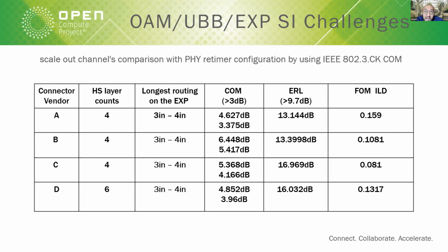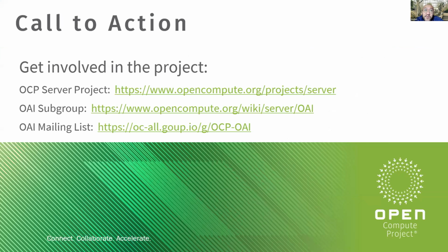Again, these are based on full wave simulation. It will have some discrepancy compared with the final measurement result, which we are working toward. Eventually, we want to do the final measurement and do the COM qualification again. Also, we want a SerDes IP vendor to do more assessment on the passive channel with their package model and their SerDes capability, whether we can reach 1E-5 BER, perfect BER, as our target, right? That's it for my part. So I will just, please take it away.